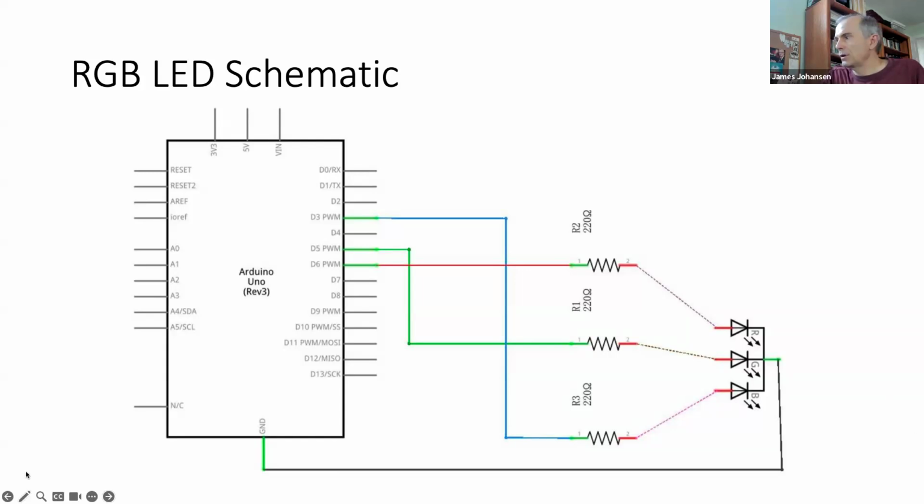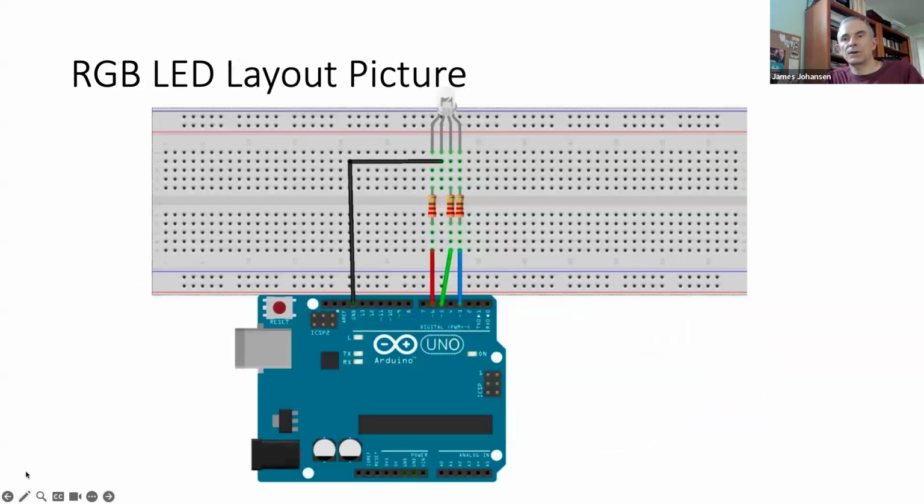The engineers are probably pretty familiar with this, but for the computer science folks, this is probably more helpful. And actually, I think for everybody, this is how you would hook together this tricolor LED, red, green, blue. You just need to make sure you get the pinouts correct on this. You have these resistors connecting to this LED. And then you have ground, and then three other inputs.